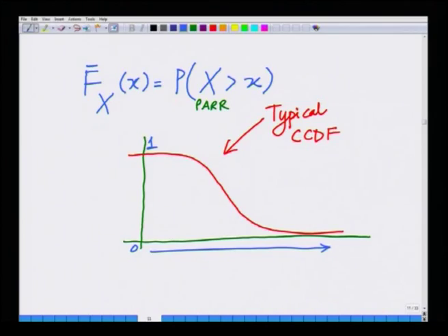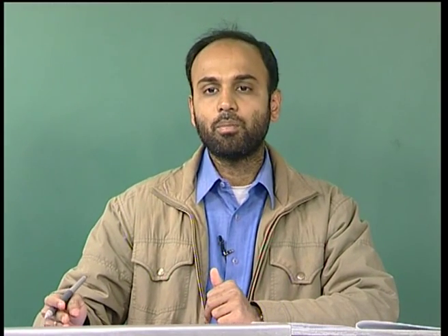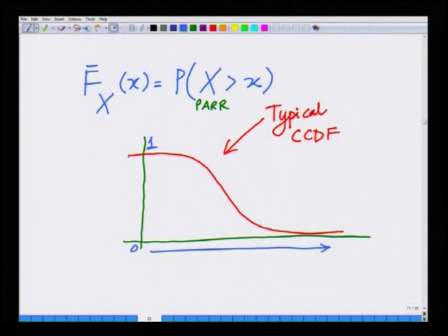So, that characterizes it, and we want the PAPR to be as close to 0 dB as possible. That is, ideally we would want this PAPR to look like this. This is the ideal PAPR characteristic, in fact of a single carrier system.